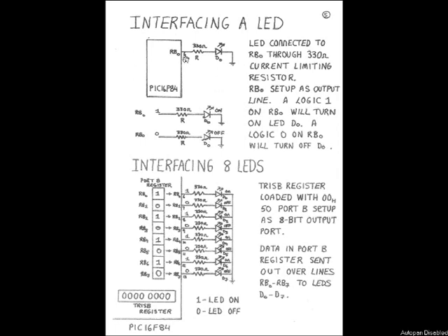So in this particular case, pin 6, which is RB0, is connected to LED D0 through resistor R. I note the D0 here is a LED because I've got these two arrows up at the top here, and these two arrows represent a light emitting diode. If they weren't there, we'd have a problem. We'd be using an ordinary diode. So make sure when you're drawing your symbol for your LED that the two arrows are there, indicating that it is a LED. So our LED is now wired or interfaced or connected to RB0.